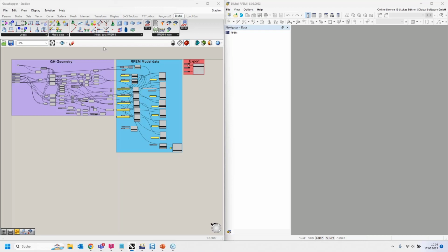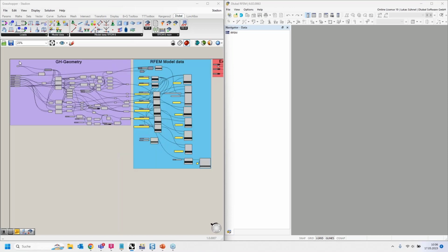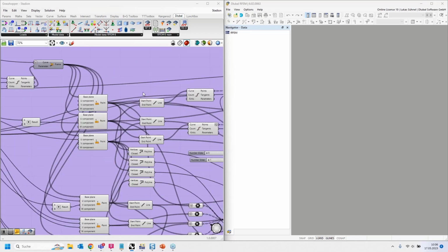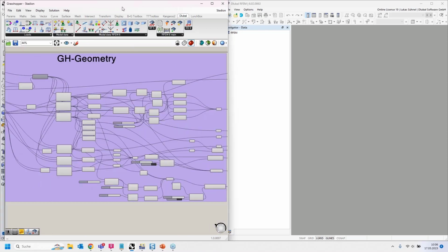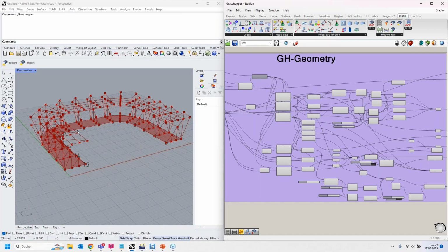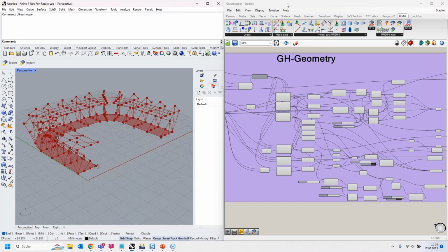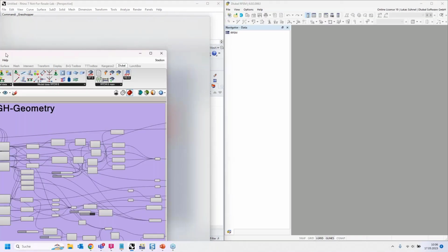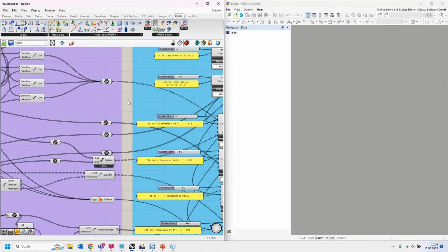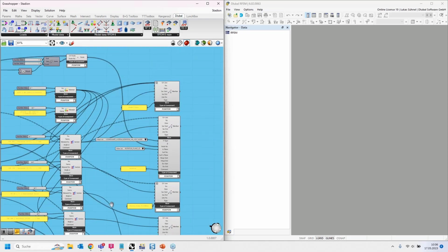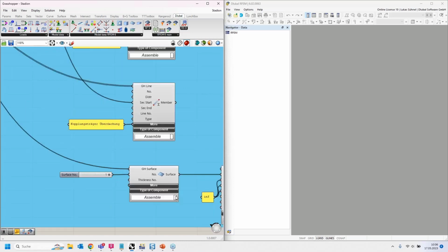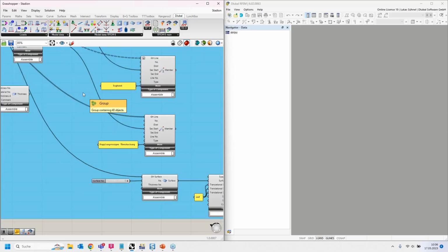How do I want to show it? Well, I want to show you first, in really just 1 minute or so, again, how the usual workflow is. Usually you would model a certain geometry via Grasshopper components. With these Grasshopper components here, with this algorithm, I created this small stadium here. You may remember it from a previous webinar. The lines and surfaces from this algorithm will then be connected to our Dlubal components for members and also for surfaces. And in those components, we then can assign the member and surface properties.